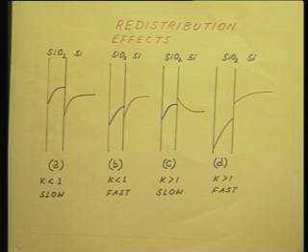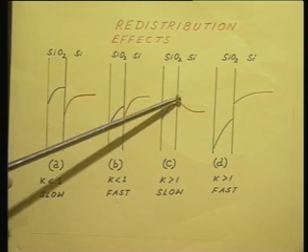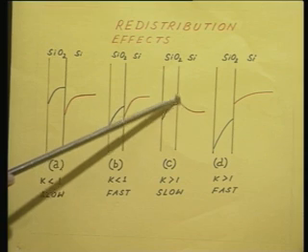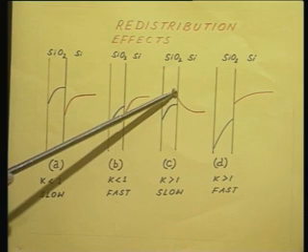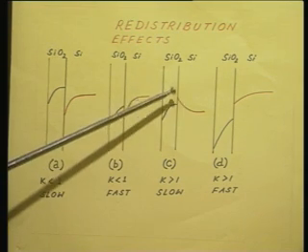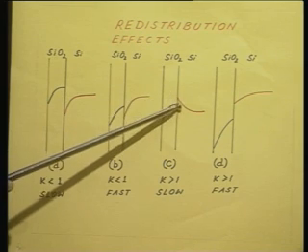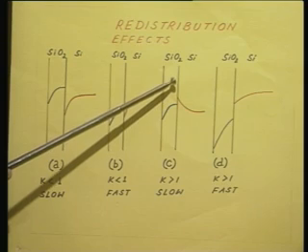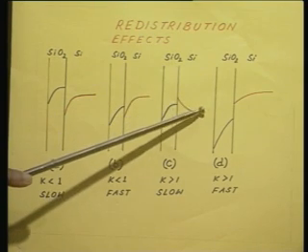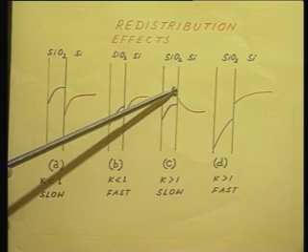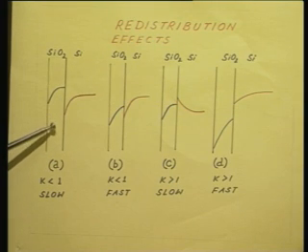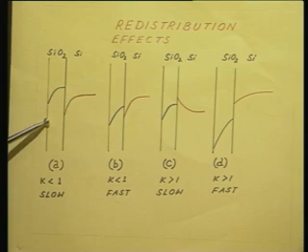In this case, what will happen? Because K is greater than 1, you see, on the silicon side I see a pile up of phosphorus, that is at the interface the phosphorus is preferentially staying back in silicon. So, what you see here is that red line moving up. In these two figures, what did you see? The red line was moving down, that is because K was less than 1.